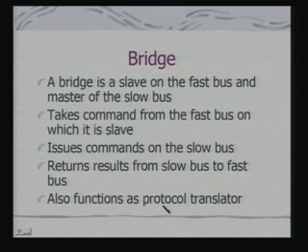In fact, the bridge you can consider is actually an additional hardware. In a very simple case, a bridge would be simply implementing a protocol machine, that is a finite state machine, but in more complex cases like the PCI bridge, it will be as good as a controller with its own registers and control logic.